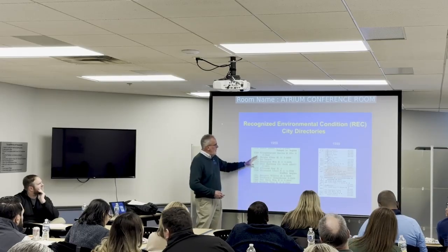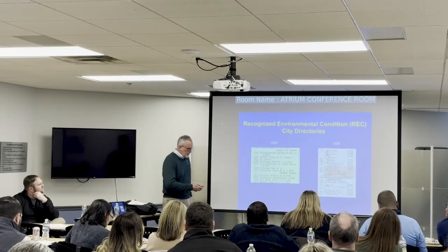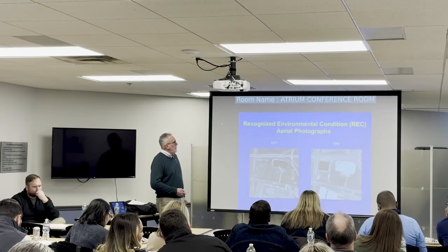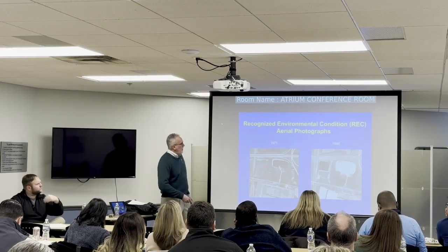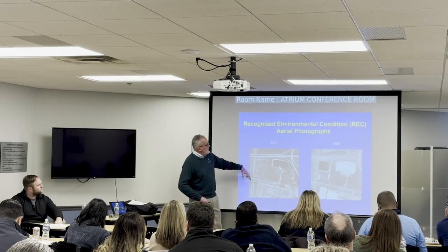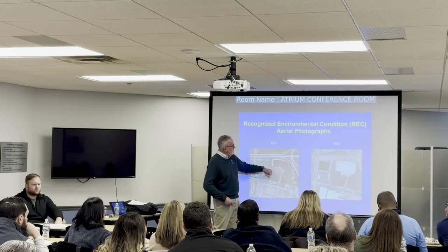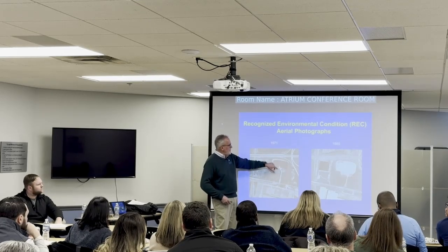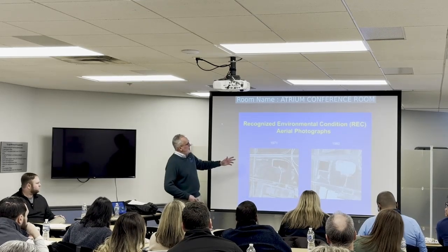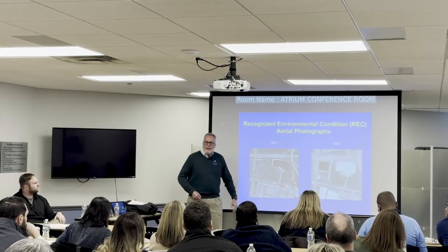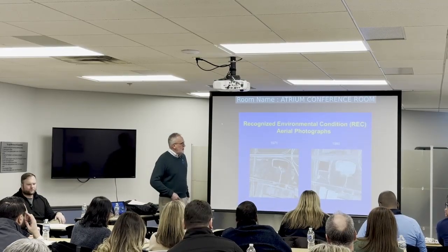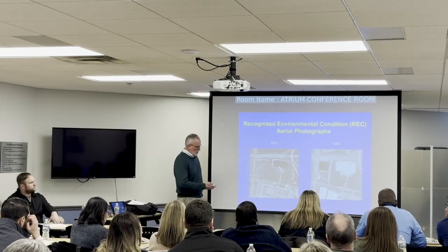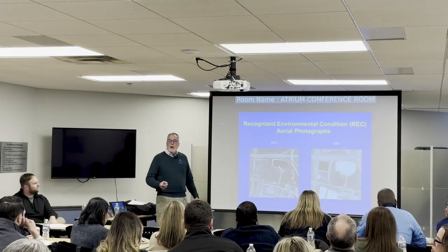There's always a lot of questions, but we just try to get a list of what the occupants at the site, what the historical use of the site and adjacent properties are. Here's an interchange. When they build interchanges, they did build embankments. They came in, built a nice pond in '71, and in 1980 it's filled. It's like, oh boy, what is that clean fill they put in there? Well, sure enough, it's a solid waste landfill. So those are the kind of things we're looking for.